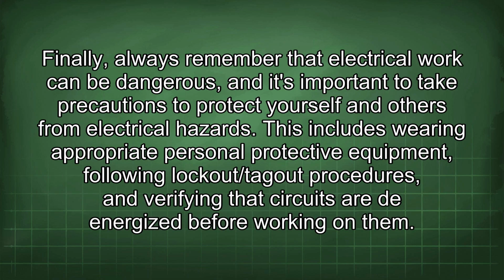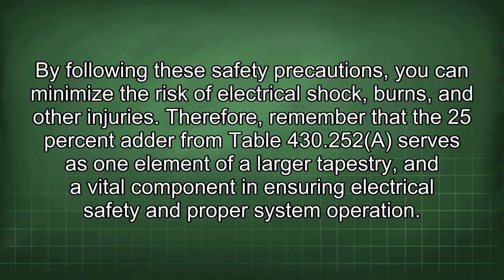Finally, always remember that electrical work can be dangerous, and it's important to take precautions to protect yourself and others from electrical hazards. This includes wearing appropriate personal protective equipment, following lockout/tagout procedures, and verifying that circuits are de-energized before working on them. By following these safety precautions, you can minimize the risk of electrical shock, burns, and other injuries.